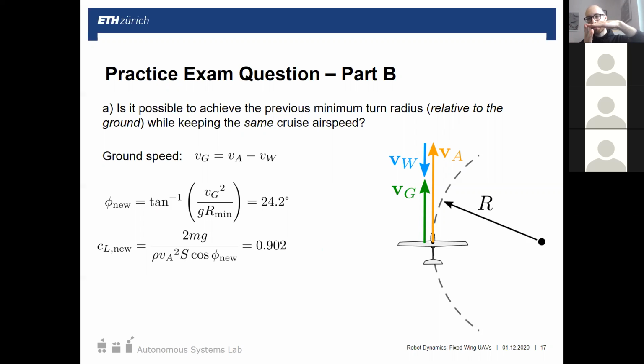The thing is, we could have something called geometric twist, which as we go further out on the wing, we start actually getting either more or less angle of attack for that chord line. And these have different stability properties depending on how the designer wants the plane to act. So that means we have different angles of attack for our chord for the same body axis. So then our definition, if we would say that the chord is always aligned with our body axis, it wouldn't be very good because we have different chords.